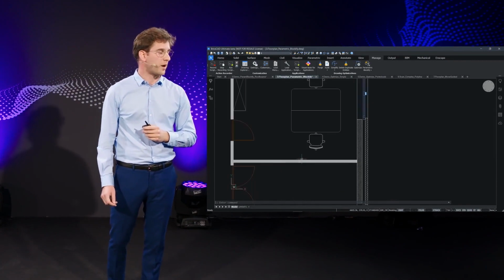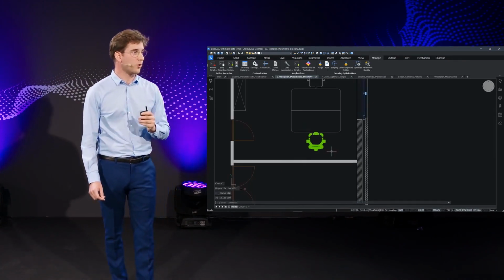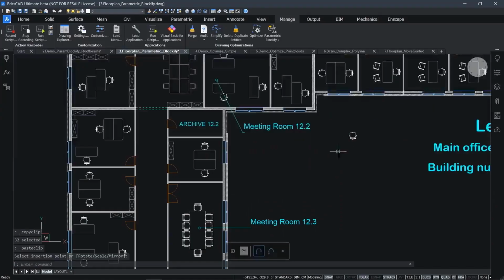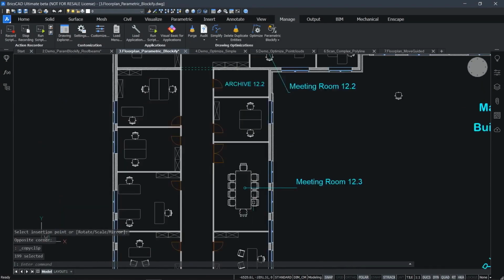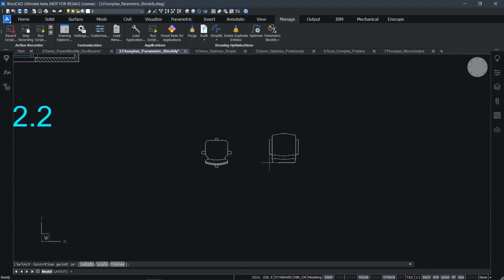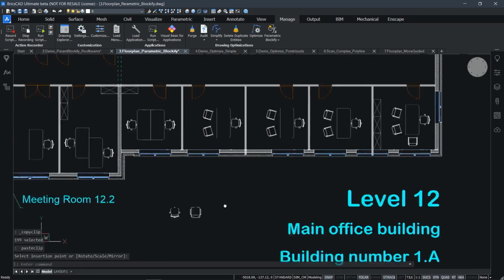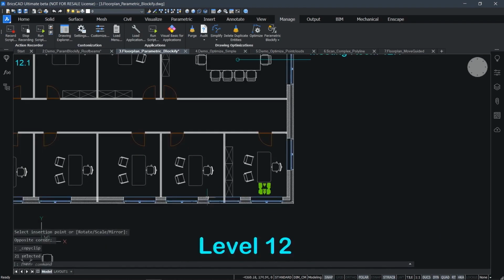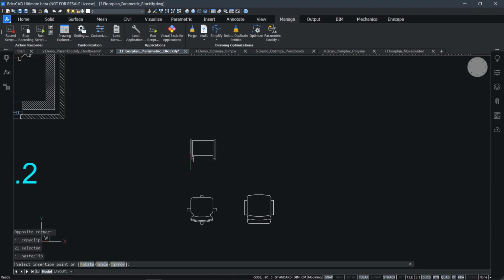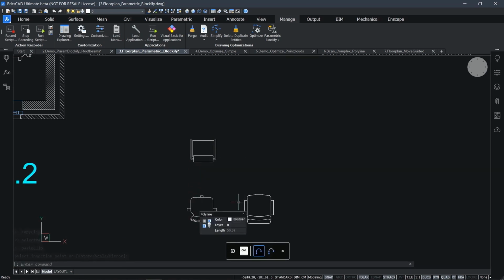All right, so during the previous part of this demo, we introduced the concept of parametric blocks, which drive both 2D and 3D geometry. So let me now introduce another property of these parametric blocks, which we call visibility states. As you can see, each of these types of chairs consists of 2D geometry, arcs, lines, and polylines. And Xian is now copying and pasting each of these chairs to an empty space in model space.